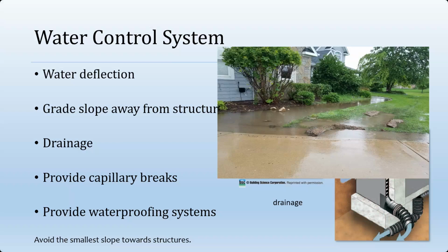And to make matters worse, they decided to drain a good portion of the front roof's elevation into a 4-inch corrugated plastic ABS type of slotted poly pipe, the 500-foot coils everybody's familiar with, wrapped in a sock.